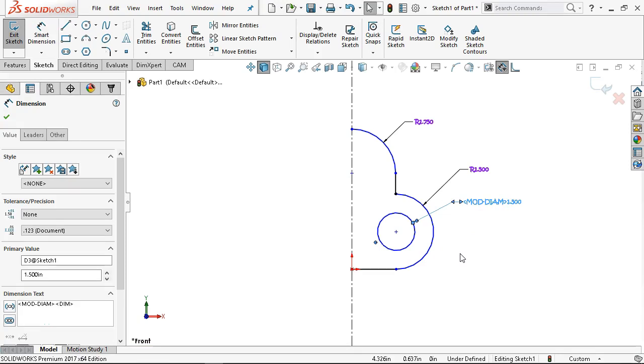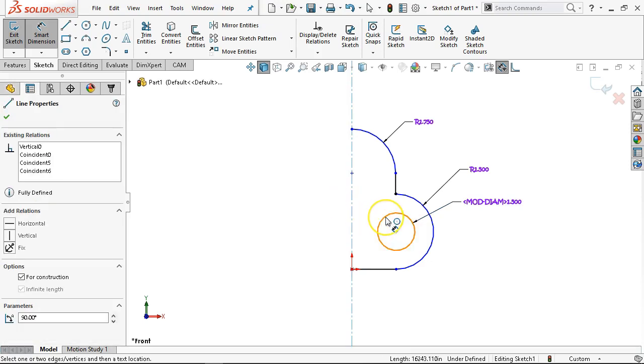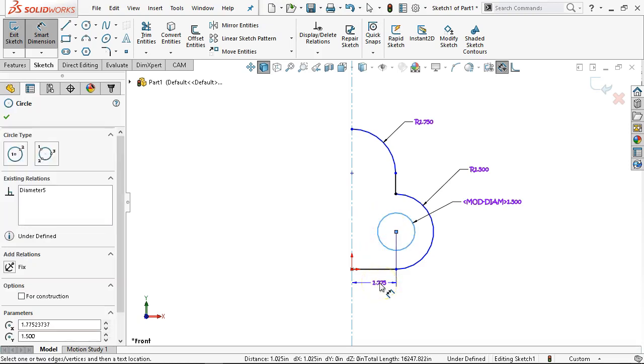Okay, so we have this dimensioning scheme. I've drawn half of my part, but I want to dimension from center to center. Well, they went center to outside, so it's just as good as an example. So either to the arc or the circle, I'm going to place the dimension. If I'm in between the center line and the object, I get the radial dimension or the half dimension, or that linear dimension. I jump to the other side, I get a diametral dimension or the full dimension across the center line.